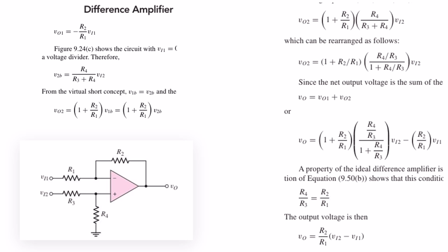So actually it will be a simple equation. In this manner we get the difference of the two different inputs. This is simply the KVL circuit only. So the primary objective, while you are solving these types of operational amplifier circuits, is don't forget to always use that since there is a huge impedance between the inverting and non-inverting terminals, the potential will always be the same. So this is the primary thing.